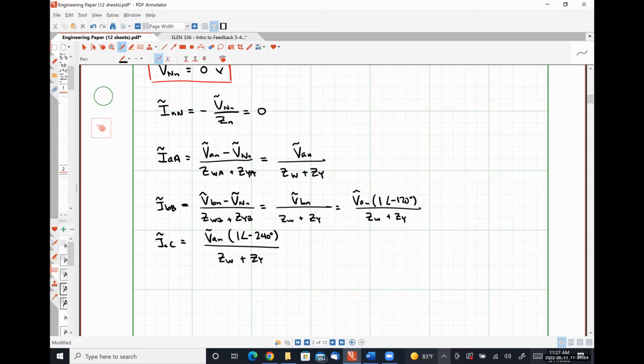That's how it has to work for a balanced system. Meaning that if you can solve for, let's say, the voltage drop over the A phase of the load, the voltage drop over the B phase of the load is the exact same thing as the A phase, just shifted by 120 degrees. We don't have to do a whole bunch of extra work. We can just analyze one portion of the circuit, and understanding that the system is balanced, figure out all the other quantities simply by phase shifting it by 120 and 240 degrees. Tie into that neutral node with a multimeter, you're going to see nothing if you have a truly balanced system, Bill.